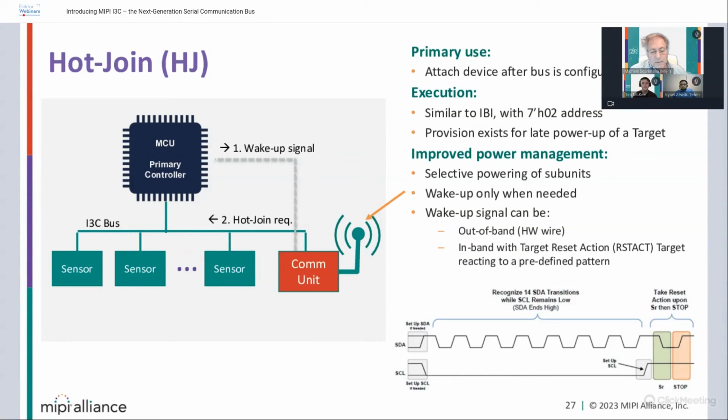So what we have here is this hardware pattern. You will see in the spec that there are similar patterns to this that are used for a number of functions, where by wiggling the data line, it performs some hardware function. In this case, if you wiggle the SDA 14 times, this can generate a reset, wake up signal to the target. So no extra wires needed. You just use the bus protocol.